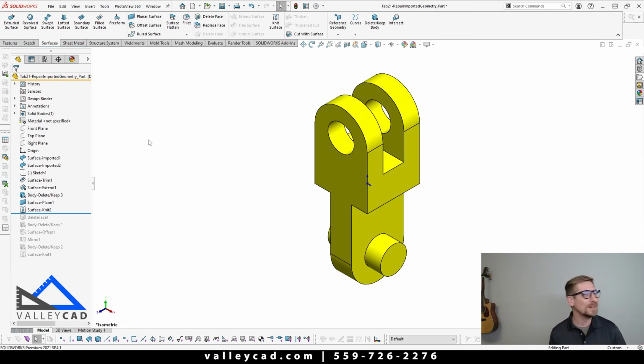Please use that tool. Then after that, if you still have some gaps or faces that are kind of being buggers, hey, go in there. You now know 2 different ways to delete faces, or you can just do a standard trim tool on a surface geometry and extend it out, and then do your normal patching operations there as well. And also use that file that we provided in a link for you. It's great practice on there.